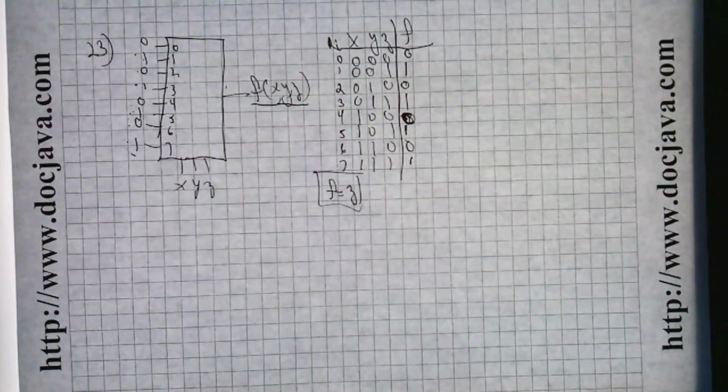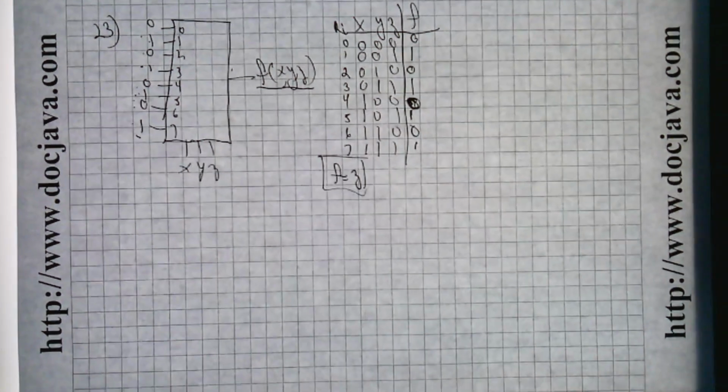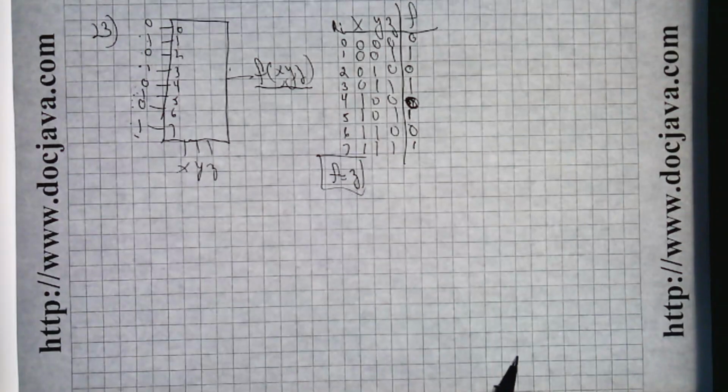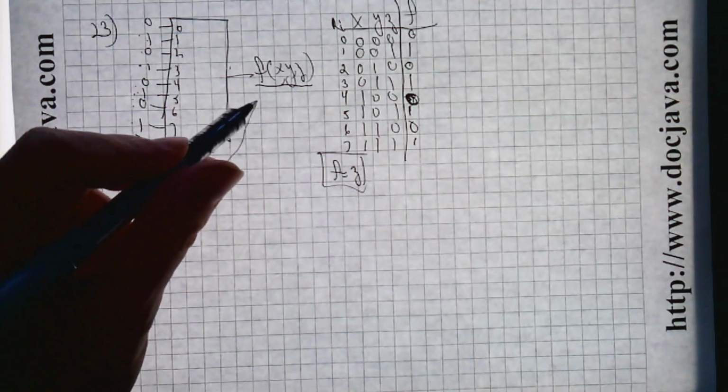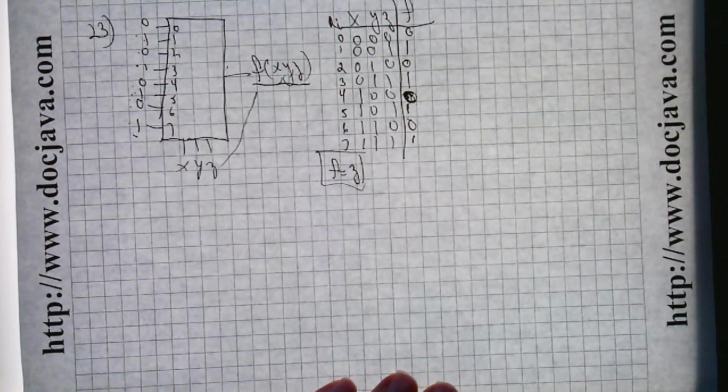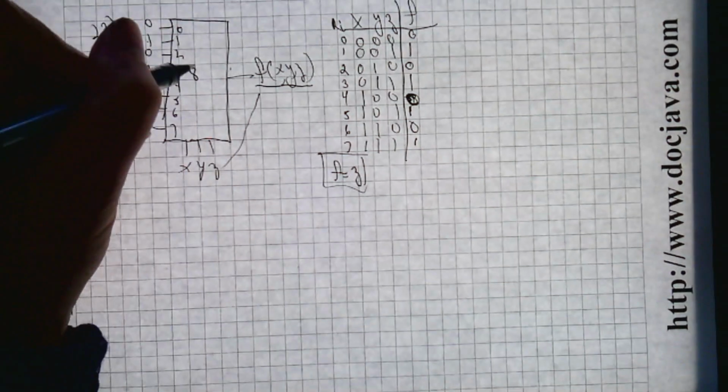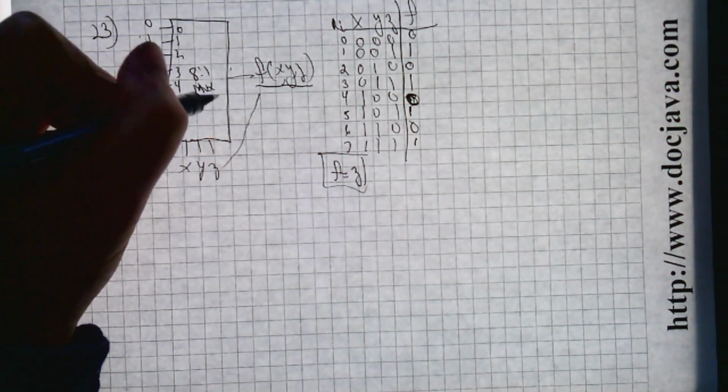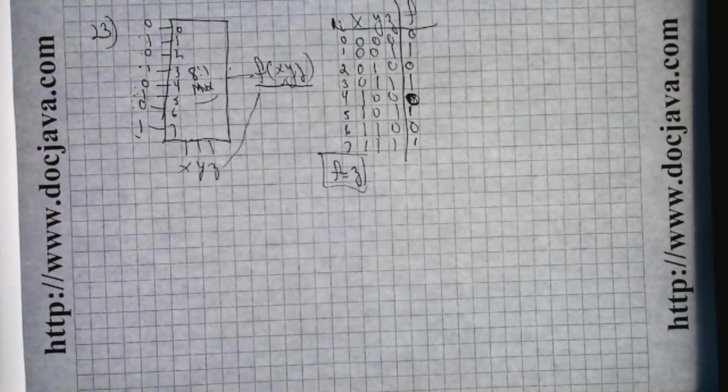And that's that. It's a wire. You could replace this whole thing with a wire. Right? Just take z and wire it to f. Bang, you're done. Don't even need the 8-to-1 multiplexer. Because that can't get simpler than a wire. I mean, that's cheap, easy to build, nice and small. It's a wire.